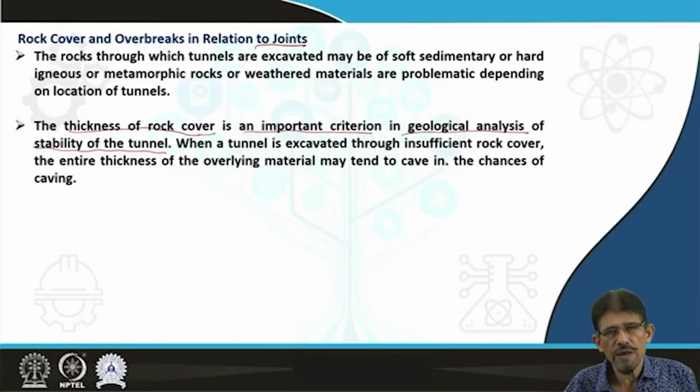When the rock cover is sufficient, it directly makes some lithospheric load on the tunnel crown. If the cover is not thick, then there is a problem of seepage and percolation, and draining of excavated tunnels is going to puncture the groundwater table and create a lot of problems. And if the strata is very thick, then it is going to create a problem in view of enhanced lithospheric pressure on this.